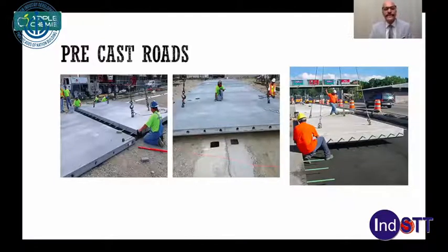Precast roads, how many? I'm not sure, but in mostly every country these days, you will find that they have done some precast roads here or there. At least somewhere 4, 5 kilometer, 10 kilometer trial roads are done, and they have been found very successful. The most important part again is very good quality and in very short time. There is a challenge, friends, when you are doing precast roads: the subbase has to be very, very good, and the base preparation. What I mean is, a fully leveled base is very, very important.